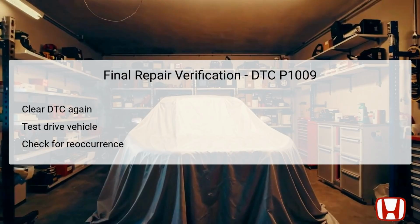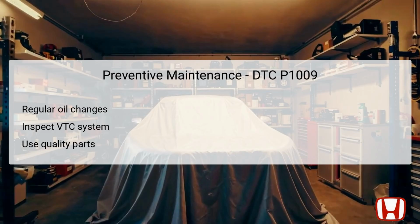To avoid future occurrences of DTC P1009 and related VTC issues, implementing preventive maintenance strategies is essential. Regular oil changes are crucial, as clean oil facilitates optimal operation of the VTC system and other engine components. Ensuring that the oil and filter are changed according to the manufacturer's guidelines helps maintain system efficiency.